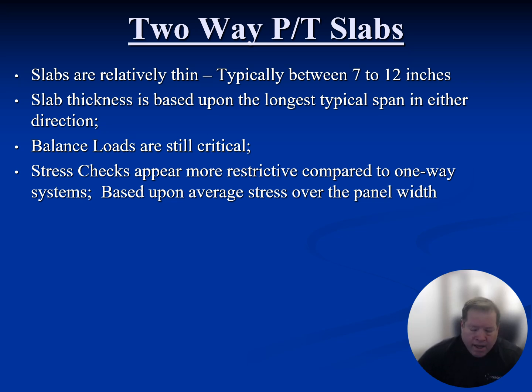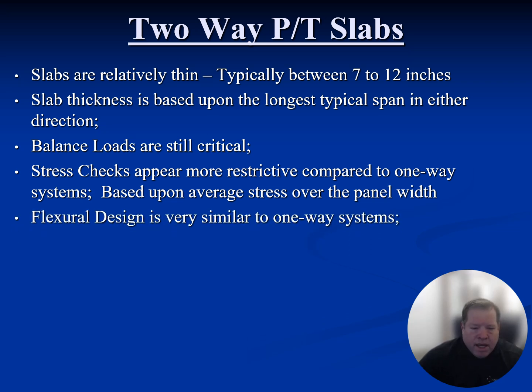And so even though the stress checks appear more restrictive, they're actually more similar than they look, and I'll get into that in a little bit. The flexural design is effectively the same. The code minimum rebar is a little different, but for the most part, the FPS equation, the Whitney stress block, all that kind of stuff is exactly the same.